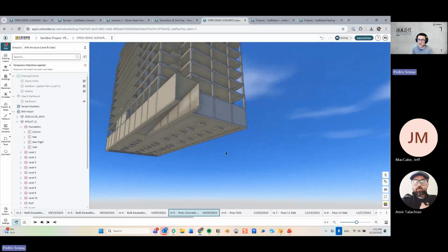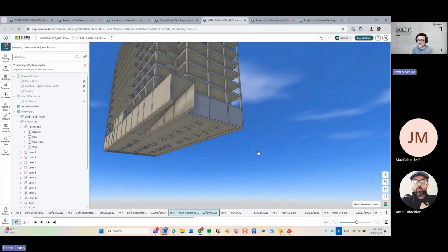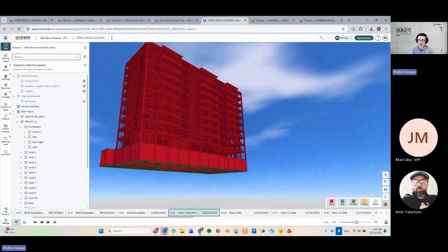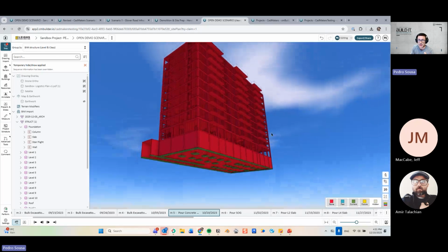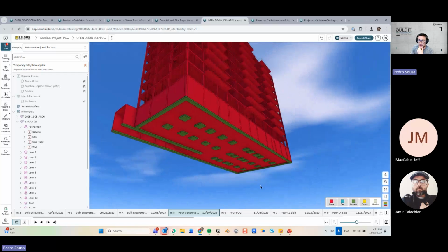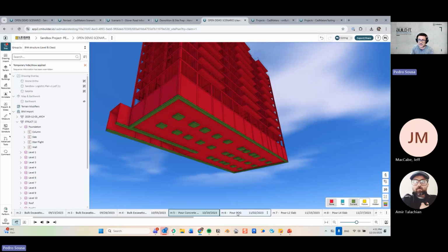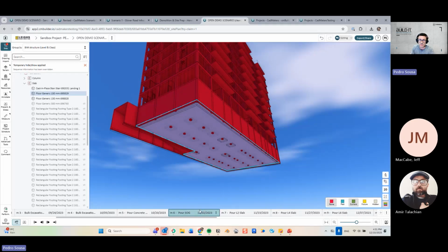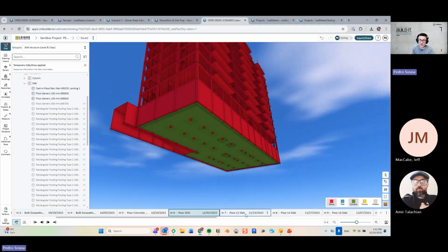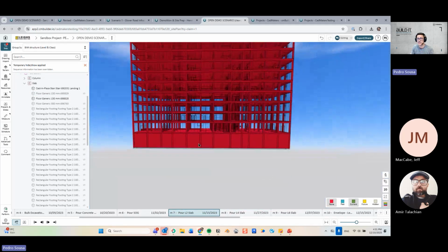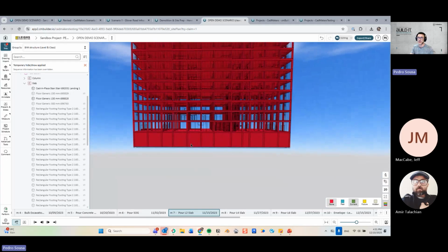But the easiest way to build our simulation here is to turn on my sequence helper, because that way I can color code by models to see how they are connected to the timeline. So everything that I see over here has a color code based on that connection. So I can easily deactivate some of these colors so I can select elements that haven't been sequenced yet. So for example, for slab on grade, I'm going to select my slab on grade and put it over here. And then when I go to level 2 slab, that element's not there anymore, so I won't make the mistake of selecting it again and putting it on another milestone.